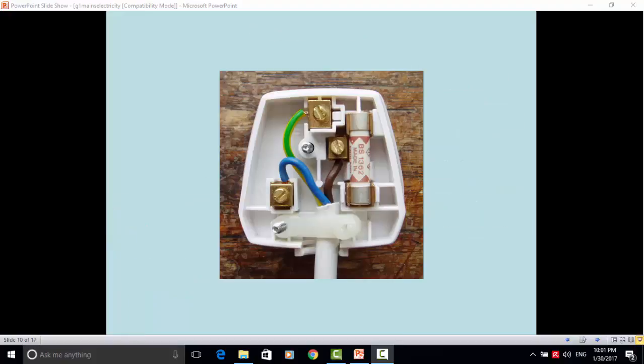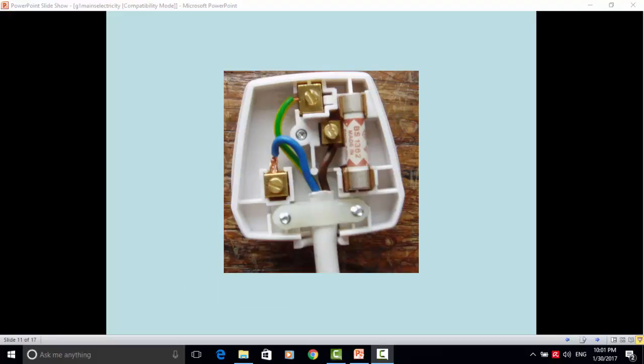I now have a few pictures of plugs that have been incorrectly assembled. You could stop the video while you identify the problem. In this case, the cable grip here has a screw missing. The cable grip should go around the outer insulation to prevent any tugging of the electrical connectors here, here and here. In this case, there's too much cable exposed at this point. There should be about this much cable, so you can ensure that the plastic insulation is not under the grip screw here.